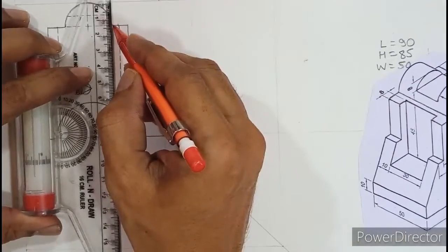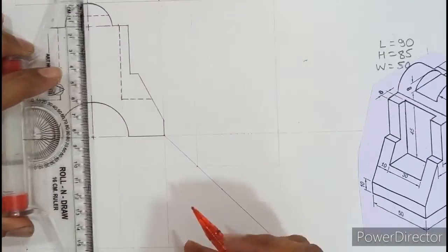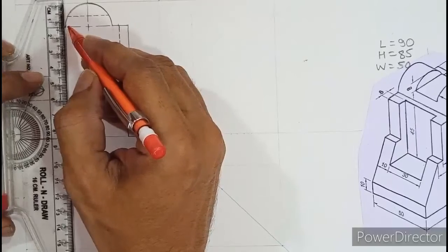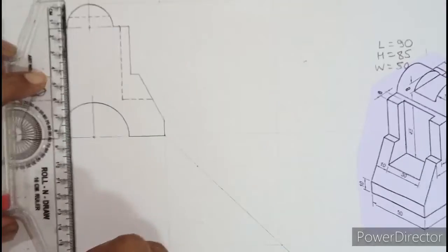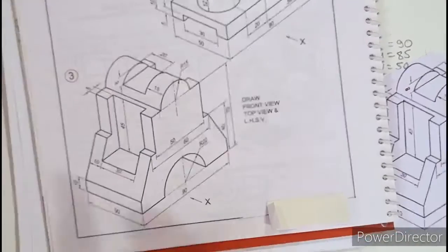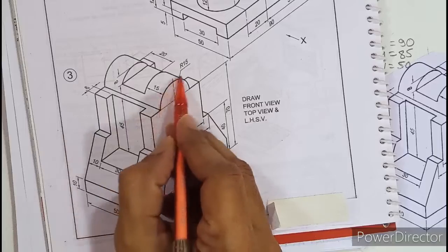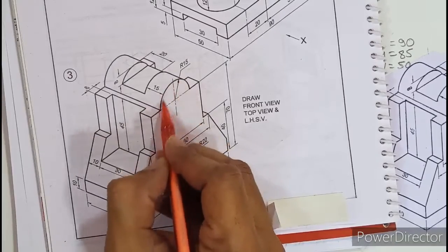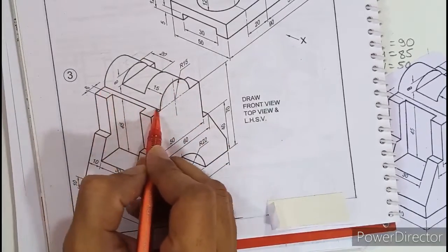So let me project this down, first and second. You need to draw step by step systematically to understand orthographics. So say I projected 2 lines down. Now, as we discussed, in the top view this semicircular edge will be seen as a straight line. Even this will be seen as a straight line. So it's a rectangle altogether.